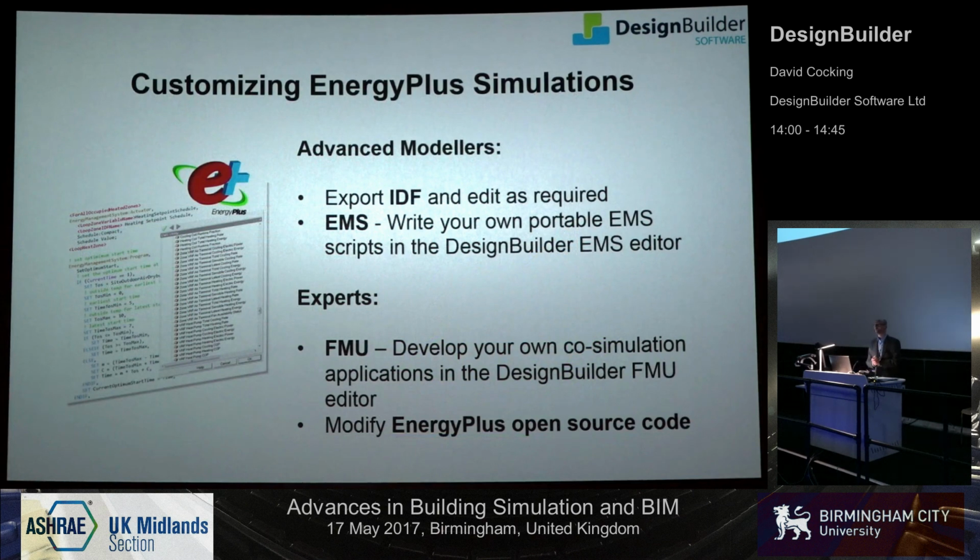There are also a lot of advanced features, so you can export the input data file for EnergyPlus and mess about with that should you want to. You can use the energy management system to write your own scripts to tailor and tweak the simulation. And then for the expert level, you've got the kind of FMU, functional mock-up unit, and all the way to modifying the source code. It is open source.